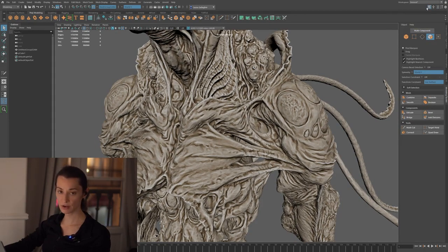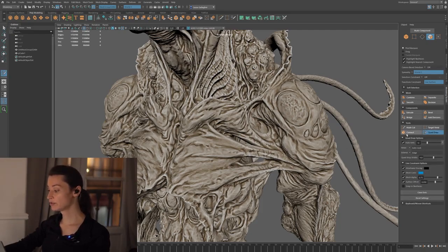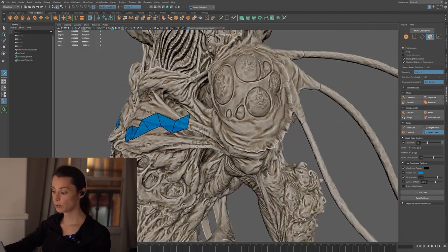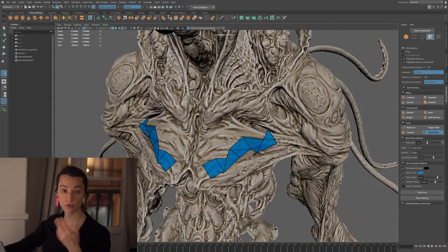So this brings out all the modeling tools of Maya. Not all the modeling tools, but some of the more commonly used ones. At the bottom here, where it says tools, you can see there's a little Quad Draw button. Just click on that to activate Quad Draw mode. Now you can start to place, move and create polygons that will snap over the surface of your object.